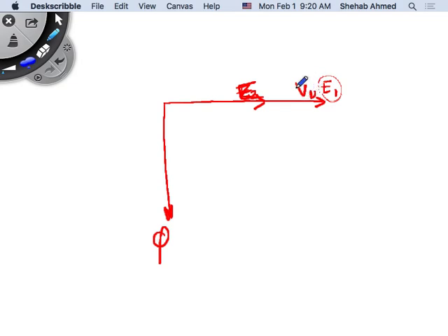This current is basically storing energy in flux, which is represented by an inductor. Current in an inductor lags by 90 degrees. So the magnetizing current that generated this flux is 90 degrees from the voltage that caused it, because I represent flux-producing components, with flux around them, as an inductance. So this voltage caused current to flow in an inductive type element and hence produced flux. This flux produced the back EMF voltage across winding 1 and the back EMF voltage across winding 2.